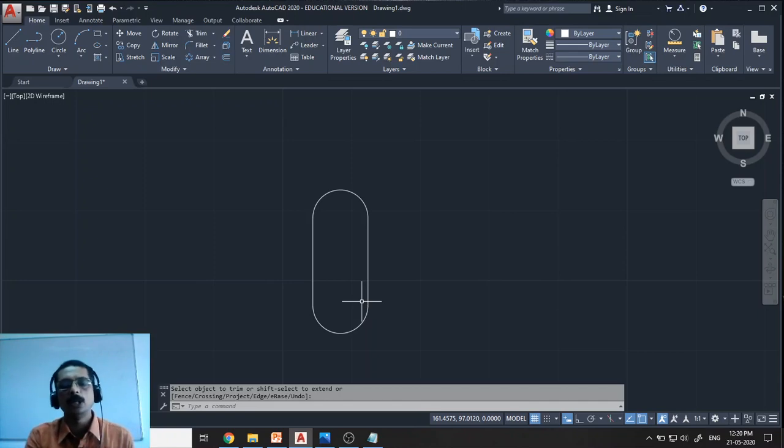we can use the polyline edit command, which is called pedit. If you use the command pedit, then you can edit the polyline. I think we have already discussed pedit. So here I'll be using pedit to join all the entities here into a single entity, which will be a polyline. Please note that none of these entities are polylines right now. See, right? So let me show you.